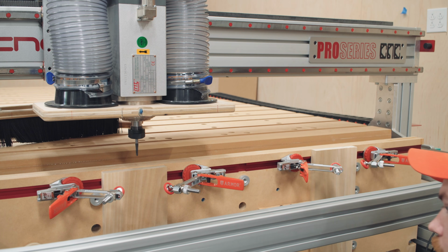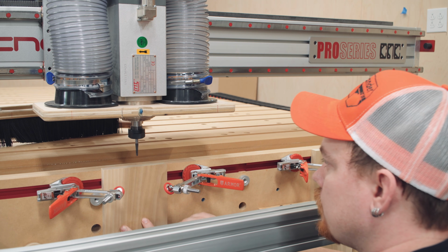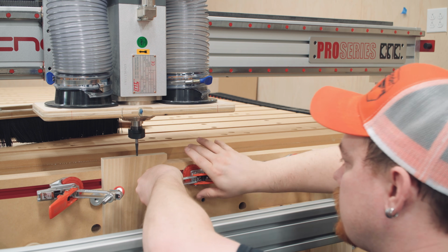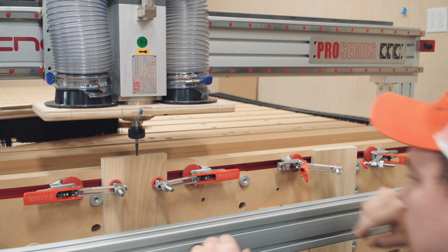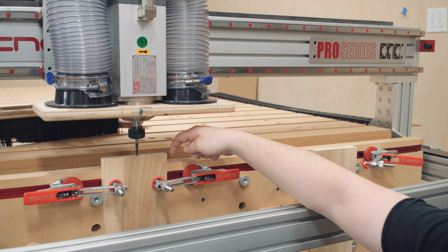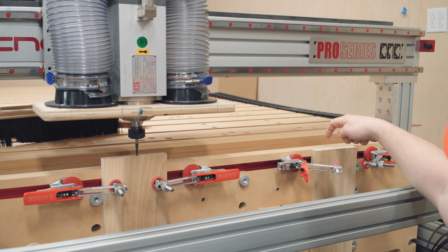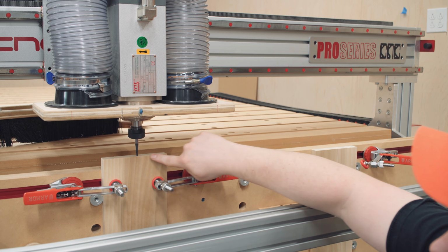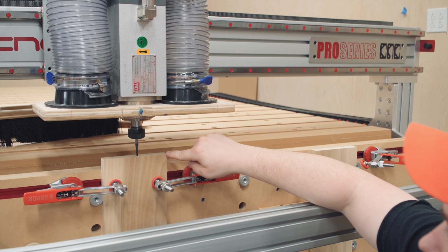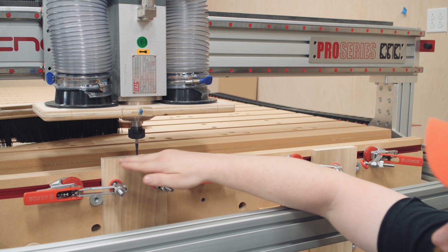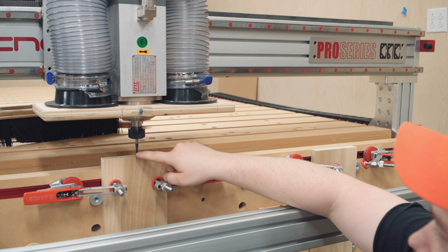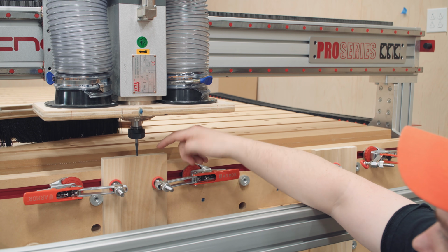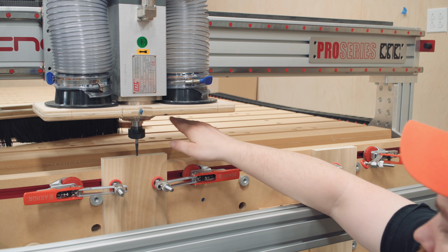So first thing, I'll loosen up my temporary clamp on the bottom, slide this up so it interacts with the bit right there, and now I can clamp this in place. That one is set, and if I simply jog the machine to the right or a positive X value all the way over to here, that's not going to be good because it's going to scratch up the top surface right here. And also, if this edge is not exactly perpendicular to this edge, let's say this is just up by a tiny amount due to either a bad cut or maybe a bad alignment over there, it's going to scratch the top surface, potentially blowing out this corner or potentially breaking the bit. Neither one of those is what we want.